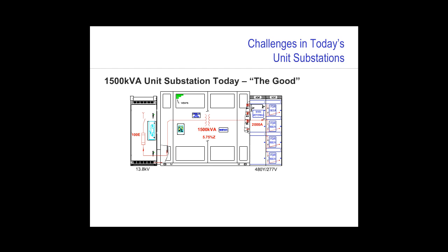The secondary switchgear could also be a switchboard configuration with group-mounted distribution utilizing molded case circuit breakers manufactured to the UL standard 891. Take note here that I've shown a vertical section connected directly to the transformer that includes main metering with a 2000 amp rated secondary bus, and then 4 feeder breakers with no secondary main, the feeders rated at 800 amperes apiece. So what do we see that's good in this assembly?